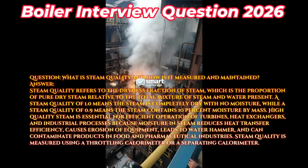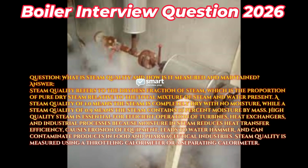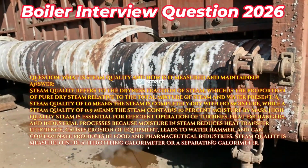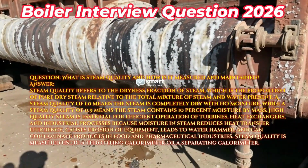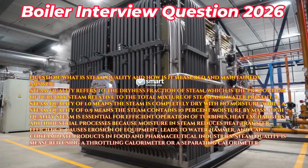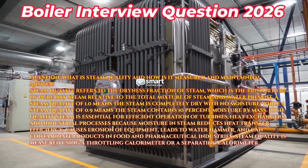High-quality steam is essential for efficient operation of turbines, heat exchangers, and industrial processes because moisture in steam reduces heat transfer efficiency, causes erosion of equipment, leads to water hammer, and can contaminate products in food and pharmaceutical industries. Steam quality is measured using a throttling calorimeter or a separating calorimeter.